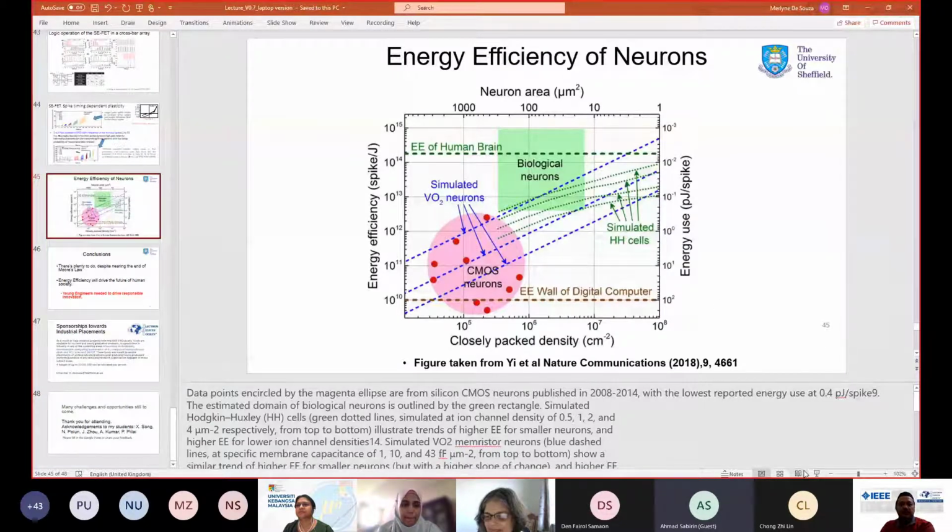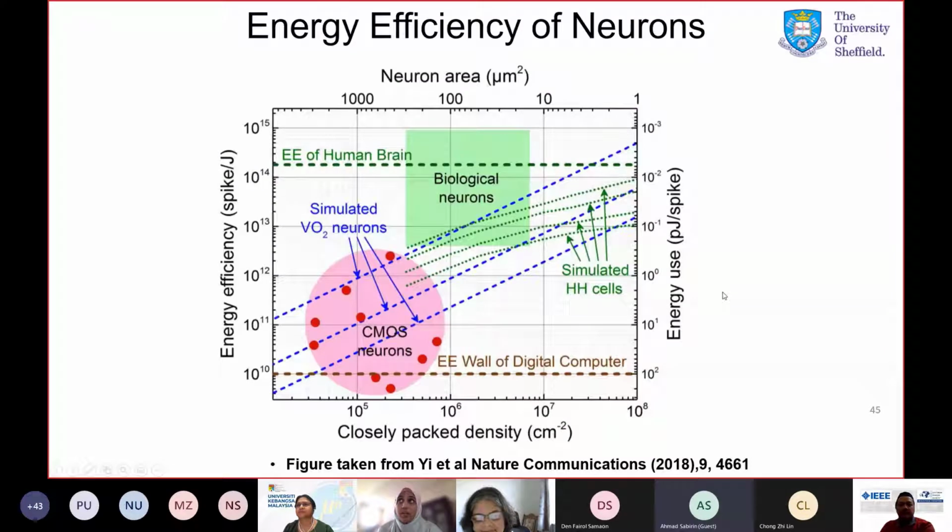You were mentioning just now that the CMOS neuron can exceed the human brain. From your experience and knowledge, when can we achieve that particular target? Okay, so these are CMOS neurons, and we really need to move away from CMOS neurons. Actually, we need new mechanisms and new types of phenomena that will beat CMOS. CMOS neurons are very expensive because you need a lot of gates in order to give that thresholding effect, that it accumulates a lot of voltage on the membrane and then spikes.